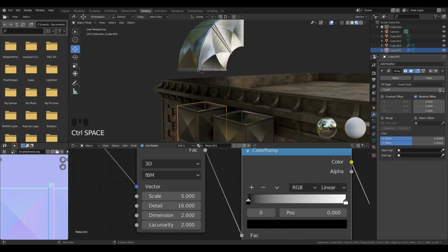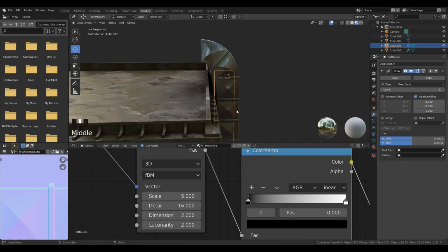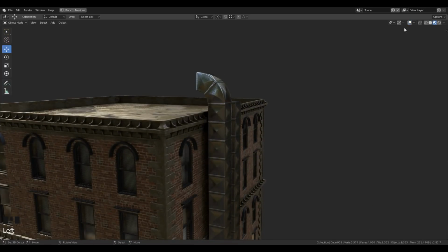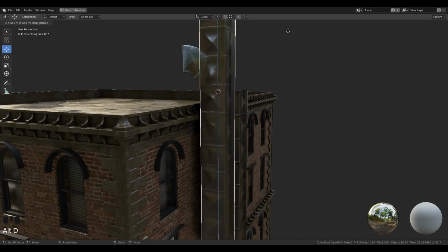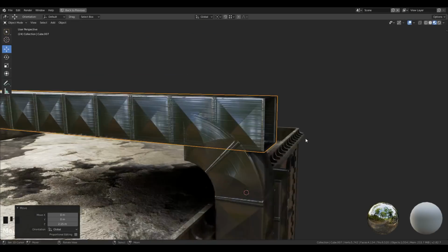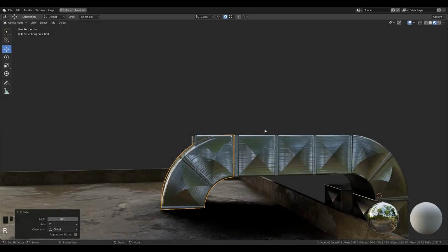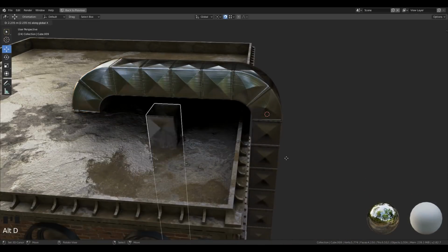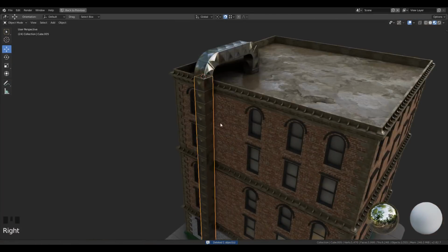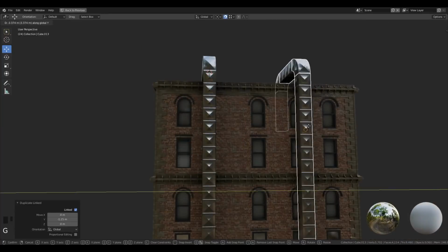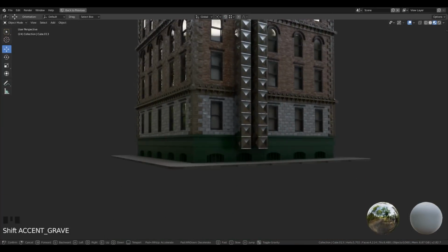Then just increase the array value of the bottom mesh to fill the gaps between them. Now just duplicate the instances and connect them with the snap tool. With these two modular assets, you can make ventilation duct to the size of anything, and you can use it anywhere and change the rotation of the second modular piece to change the direction of the duct. You can set any length to it.